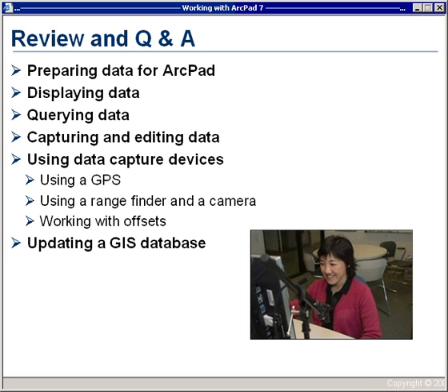PDOP is just one of them, and often may not always be the most significant issue. The quality of your GPS receiver, the size of your antenna, the troposphere conditions, if you've got multipath rejection, if you're working under canopy, all of these are variables that impact your accuracy. So going just by PDOP is not a sufficient indication of accuracy.